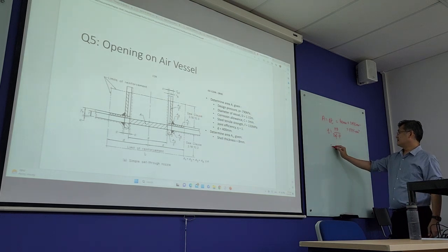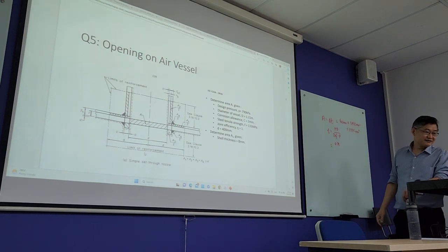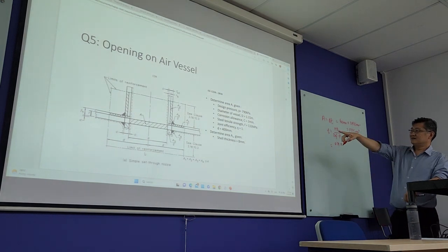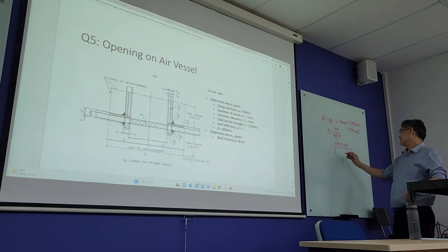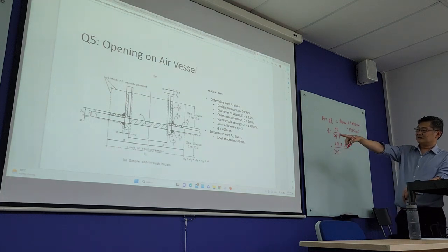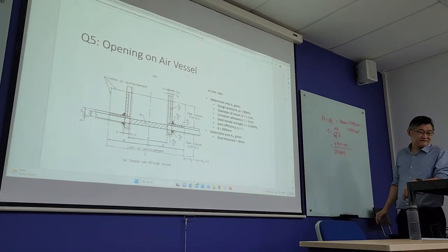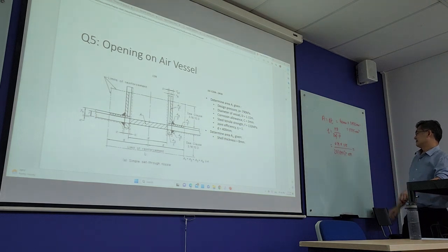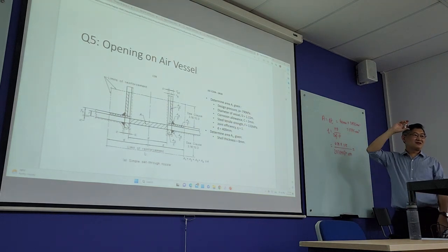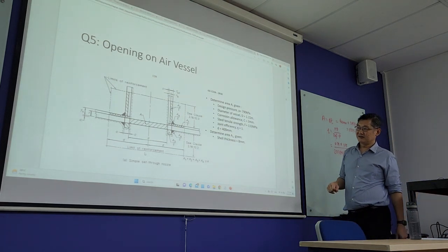Because from here, this is your design pressure, 0.79, times your diameter given, 1.15, then efficiency 1, then tensile strength 133, minus 0.7. So this is the thickness that withstands the design pressure. That's what they show here.